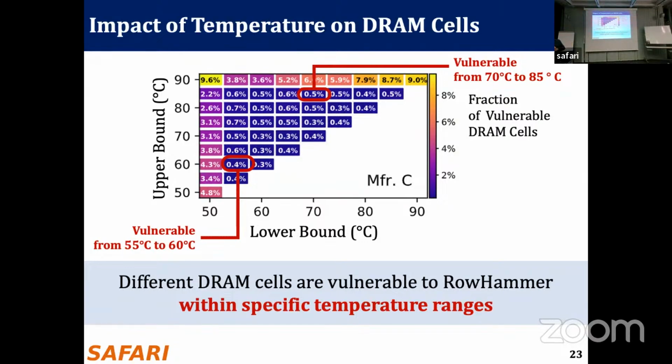So how do you know what the actual upper bound temperature is? Well, we do not know, but this is basically a reasonable upper bound for operating temperatures. So you usually don't go beyond 80, actually. But what is the maximum supported temperature for these chips? I believe for these chips it should be like 95. And do you need to increase the refresh rate after 85? After 85, you need to increase the refresh rate.